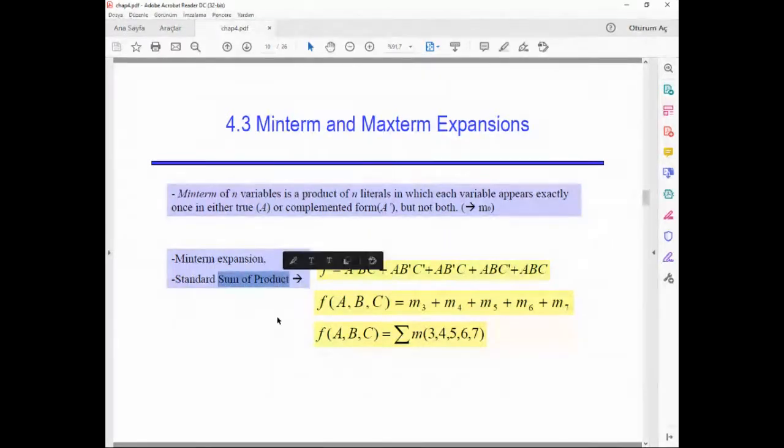In the sum of products, you just product the inputs. You use AND gates for products, like multiplication, and take it like a variable and do the same for all of them, and just sum the products. Sum means plus, so it means OR gates, right? Sum of the products, you first do the product, it means multiplication, it means AND gates, and you sum all of them. Just use the OR gates, just use the plus.